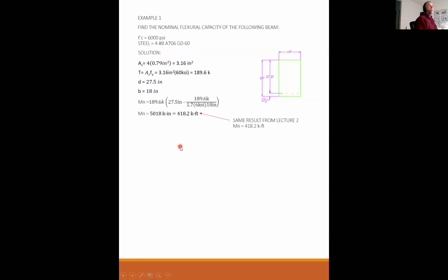We're going to go into a whole other realm of design. So you have analysis and you have design. When you design a beam, something will not be known. And in some cases, multiple things will not be known. For example, maybe all of this is given to you, but we don't know how much steel you need. Or maybe all of this is given to you except for D, and you don't know how much steel you need. So we're going to go from the simplest, which is analysis, to design. Now, again, please keep in mind that every design problem is going to end with an analysis problem. Every design problem, you're being called upon to design the beam. And once you come up with a design, the last thing you have to do is the analysis to make sure that you have sufficient strength. And we'll have lots of examples to show that.